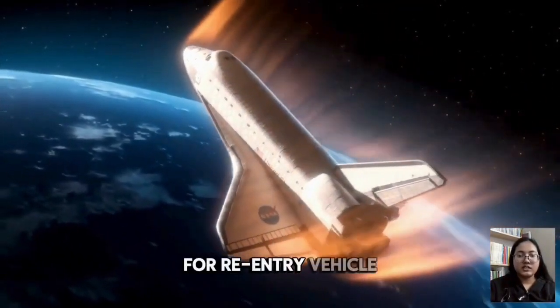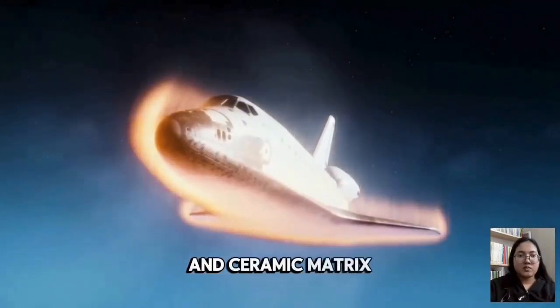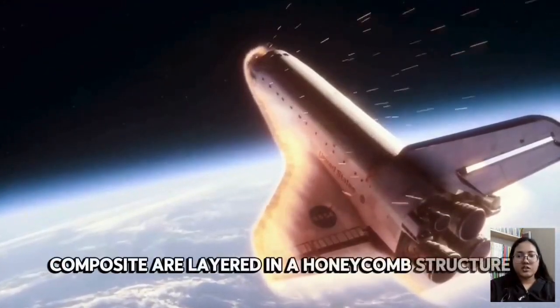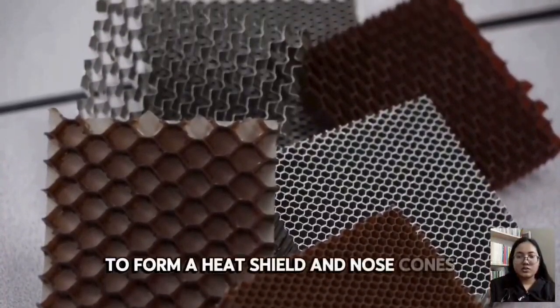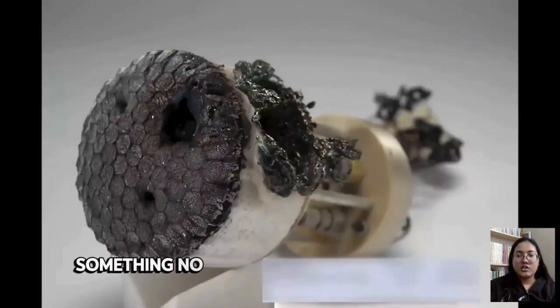For re-entry vehicles, according to a study by Frankel and Burnett, carbon-carbon and ceramic matrix composites are layered in a honeycomb structure to form a heat shield and nose cones, withstanding temperatures of 1600 Celsius, something no ordinary metal could handle.